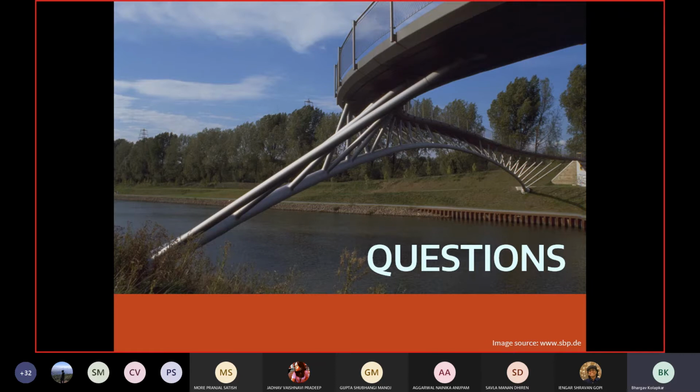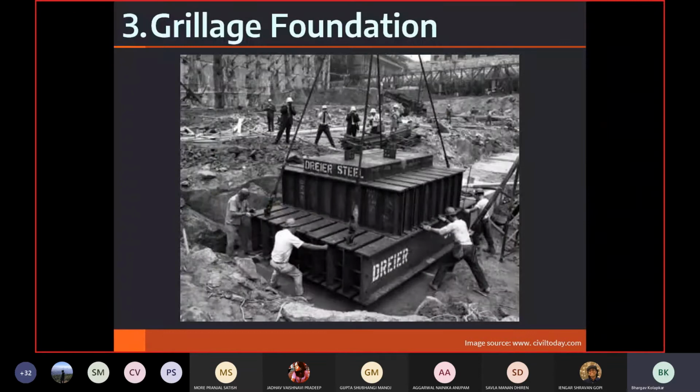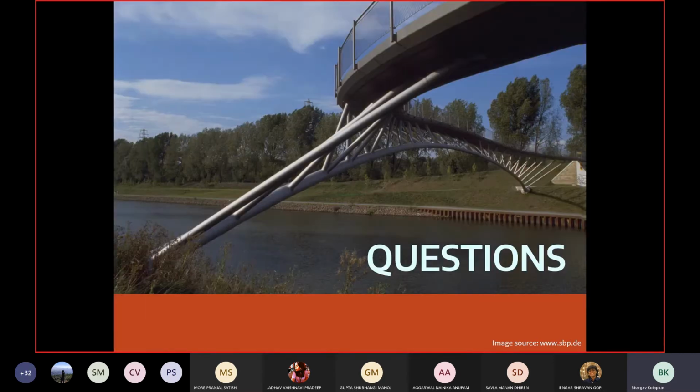But in a reinforced concrete footing, concrete has a structural function. Concrete resists shear, concrete resists flexure, and you design a footing just like an inverted beam. Here, the entire point of providing concrete is to protect steel from water, from soil, in short, from corrosion. It does not have a structural role to play. Do you understand the difference?